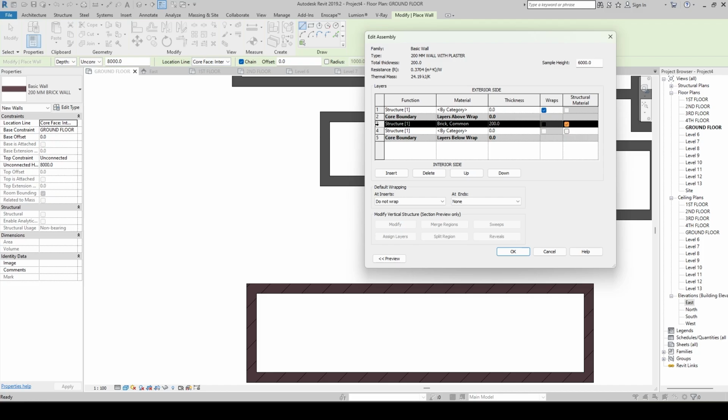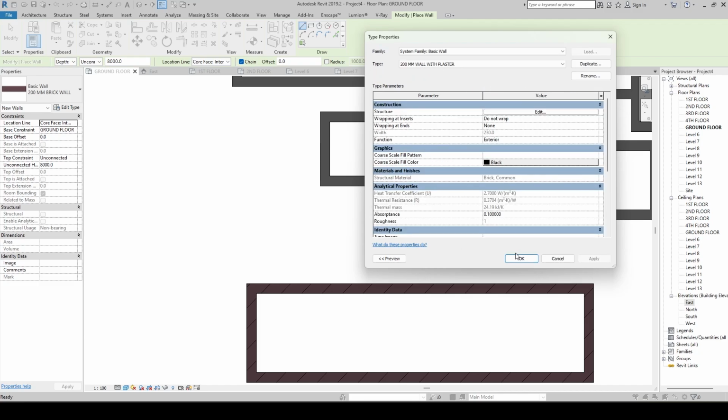So basically this is the structure. Column number 1 and column number 4 are the finishing items. Column number 1 is fine, but it is being laid above the structure, and here it's overlapped. So I want to make sure that this has to come down. Okay, now this has been arranged, but I need to assign the value. What is the plastering thickness I want to assign here? Maybe I'll assume 15 mm. Then here as well I'll enter 15. This is the structural, and these two are the wraps or maybe the finishing materials. I just need to simply click on okay.